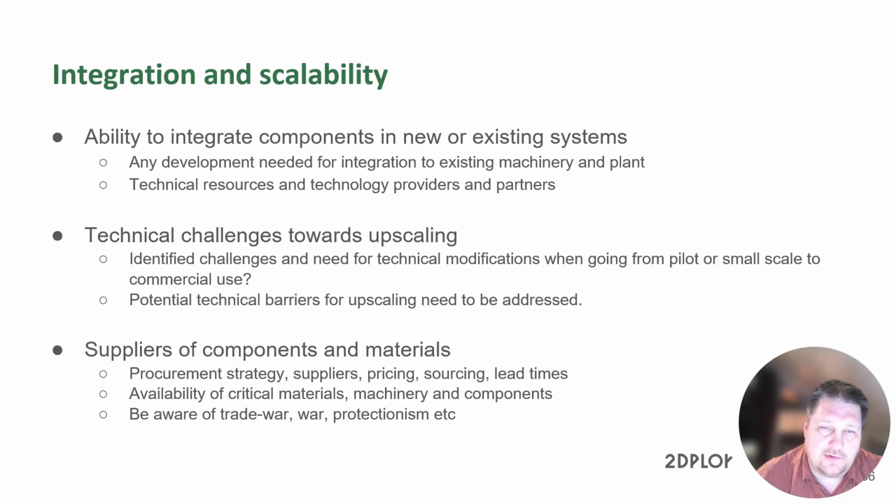Sometimes you need to rather keep the same size but multiply the number of units, maybe due to some physical limitations or other things. So you need to have good control of your upscaling philosophy, both on what you want to achieve, but also what is physical, practical, economical, beneficial in such upscaling.